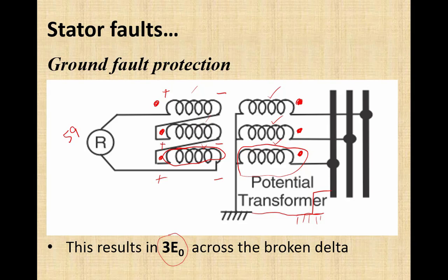If we connect the three terminals to the ground through those stray capacitances, third harmonic will take that capacitive path instead of passing through the three windings of this voltage transformer, because it is highly inductive. It gives a very high impedance path for the flow of third harmonic current. So due to this reason we were getting zero voltage when all the stray capacitances were in service, and we get a voltage even in normal condition across this relay when all the stray capacitances, line to ground capacitances, were removed.